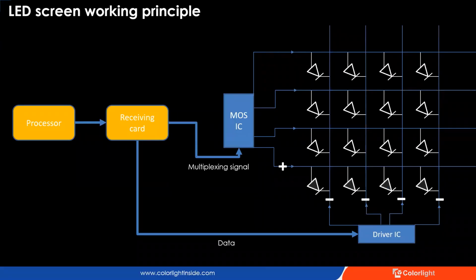Imagine that if this cycle is completed in 4 seconds, so each LED's on time in a row is roughly 1 second, your eye would perceive it as flashing. Now, if this happens fast enough, then your eye doesn't perceive it as flashing, but rather perceives it as on. For example, it's just like setting the camera.